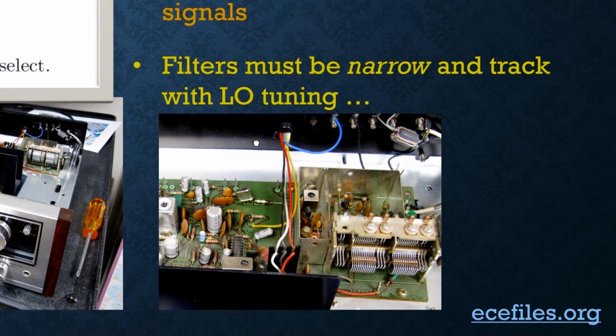And then I have a blow up of it here. So this is where the antenna comes in. There's a balun here for the 300 ohm case, and then it's converted to 75 ohms. It comes in on this little coax. It goes into the low noise amplifier cavity. I've got these shielded cavities here before it hits the mixer, which is over here. But there are inductors in this cavity, and they resonate with variable capacitors.